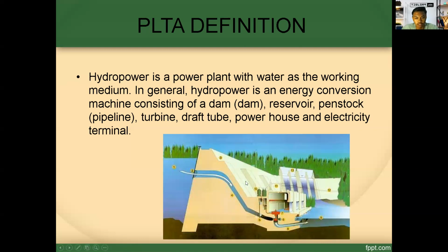equipment beside the generator. The working system is to utilize the flow of water from the river, which is then accommodated in a dam, which is then flown into a series of pipes, so that the potential energy of the water can be converted into kinetic energy, so that it is eventually converted back into mechanical energy to drive or rotate a turbine.